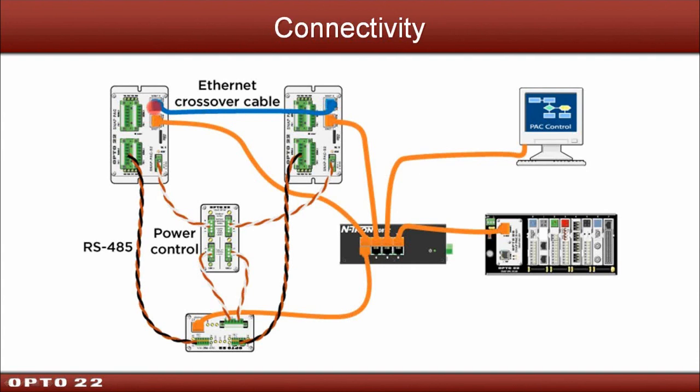Now, one thing I should mention is that this information that goes over this crossover cable network is very, very high speed. It's not TCP IP. It's essentially down at the MAC level. So this communication is very, very fast and not subject to normal TCP overhead that you would find on a standard Ethernet network. That said, it's just Cat5. So it's not a special cable that's required, and we found no benefit to going to, say, a fiber link between these two, as we've seen from some other redundant systems that are on the marketplace.